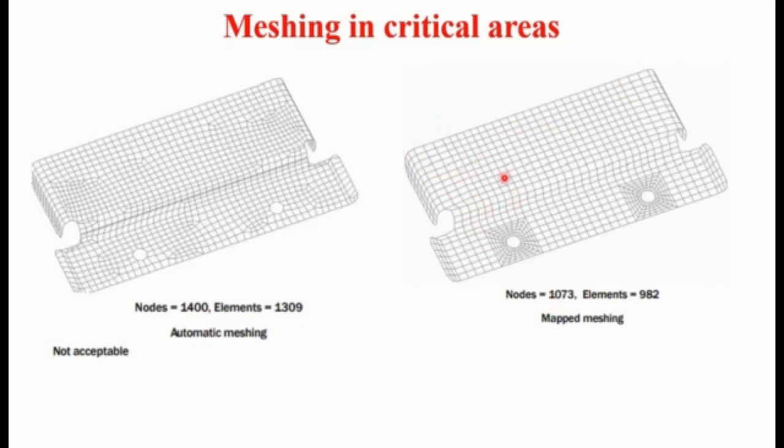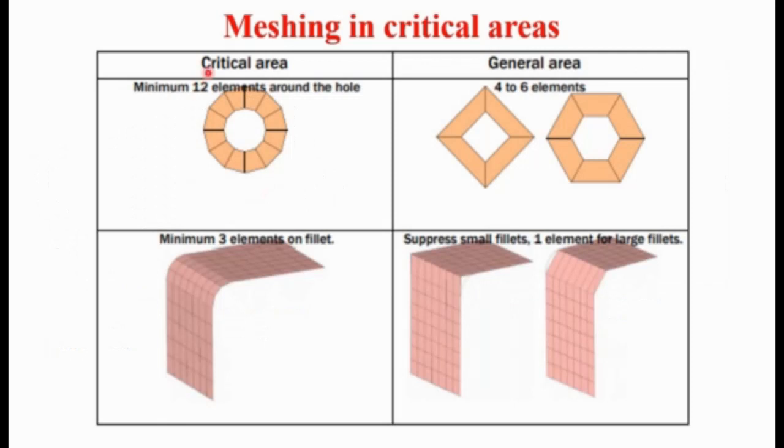In these pictures, it should be a straight line or in a proper way. Whenever there is a hole, only in that region do we have to change the meshing, or fine meshing should be there at the holes or any other change in size.